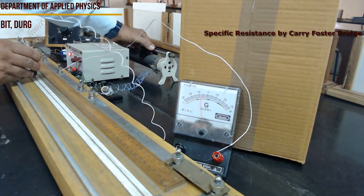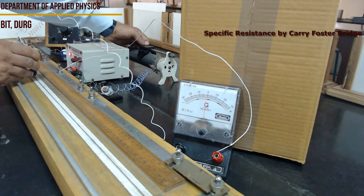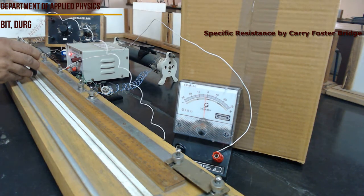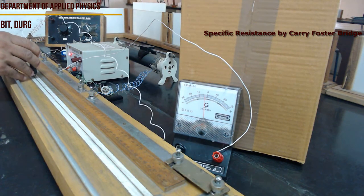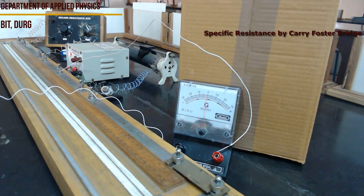So I have kept the jockey exactly at the center of the wire, and by varying the rheostat, I have brought the galvanometer reading to 0. This is the first adjustment, and you have to do it only the first time. Next time you are never going to change the position of the rheostat. The rheostat is now fixed. It is never going to change throughout the experiment.